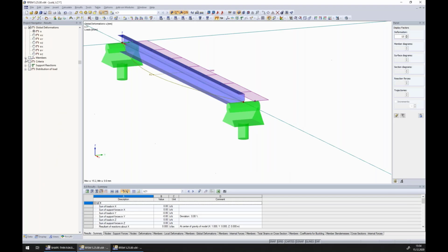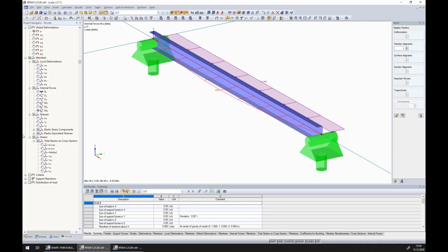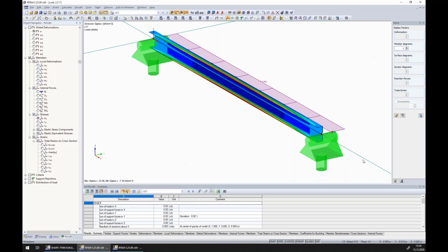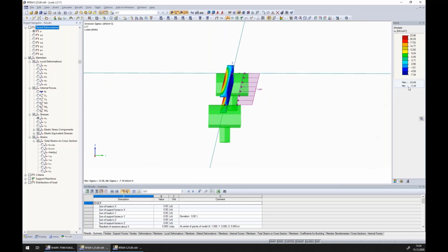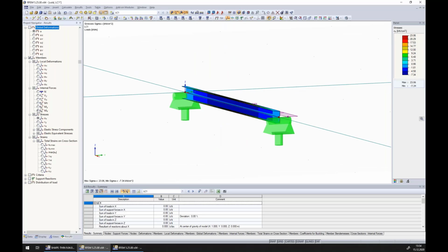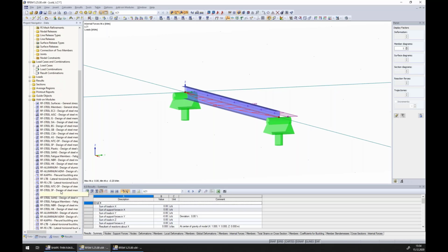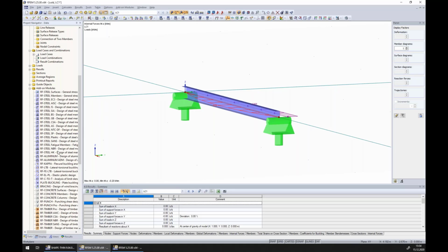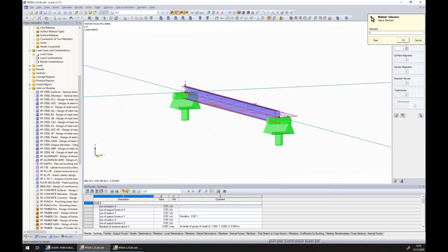Let's check. Members MC, so we have here a bending moment of 0.2, and the stresses to check if we applied it right, we get on the back in the web again compression stress. So far it's good, and now we can do the same cold form design with all properties that we defined in SHAPE THIN for the complete member in Steel Easy 3 by applying this member for design.